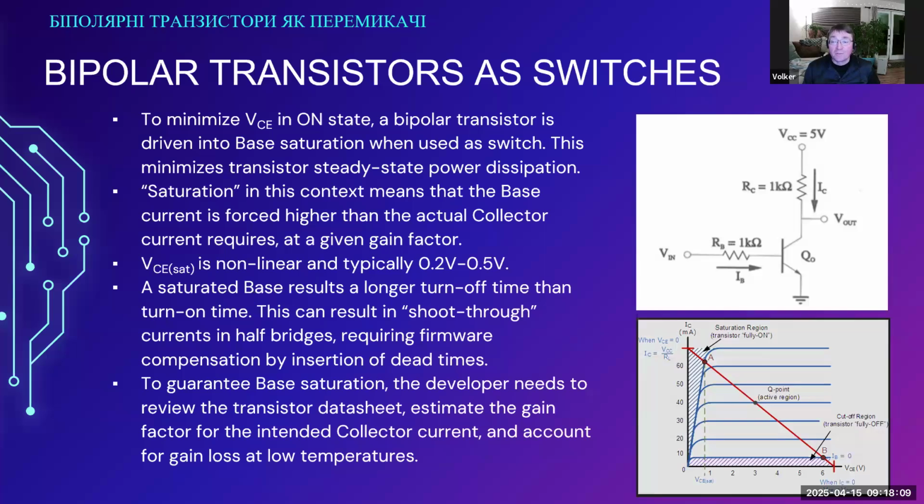The transistor has, and you're assuming the transistor has a gain of 100. So you take the voltage of the microcontroller, which, for example, is 3.3 volts. You subtract the voltage of the PN junction, which is 0.6 volts. So now you're ending up with 2.7 volts. So you can expect the base resistor to have a voltage of 2.7 volts.